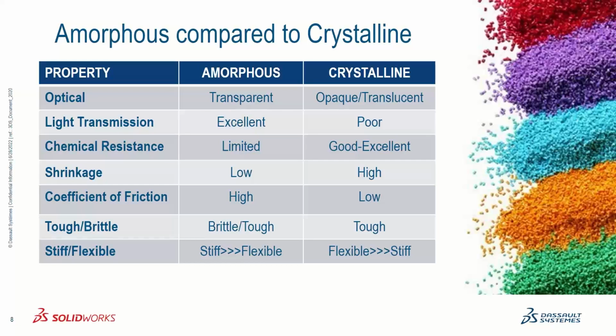Semi-crystalline polymers tend to be anisotropic in flow, which means they exhibit greater shrinkage transverse to the flow direction compared to the flow direction. And because of this anisotropic shrinkage, this can sometimes result in dimensional instability. It can lead to warp, something that as a designer, if you're working with semi-crystalline material, you'll have to account for, that the material is going to shrink differently in the flow direction compared to the cross flow direction.